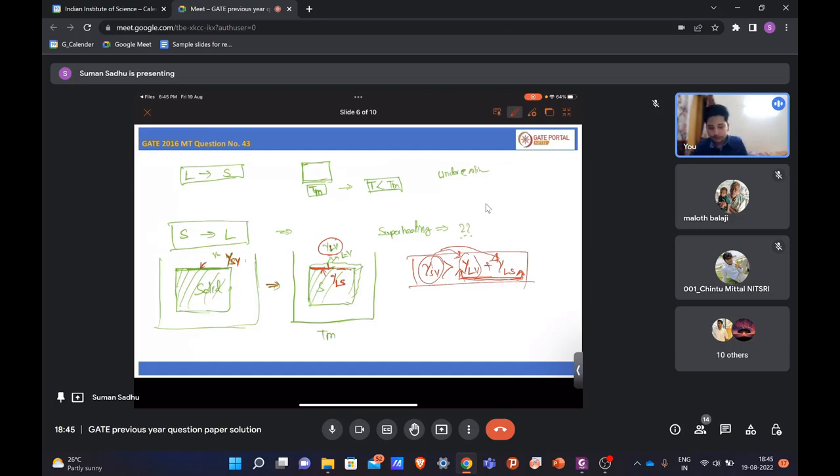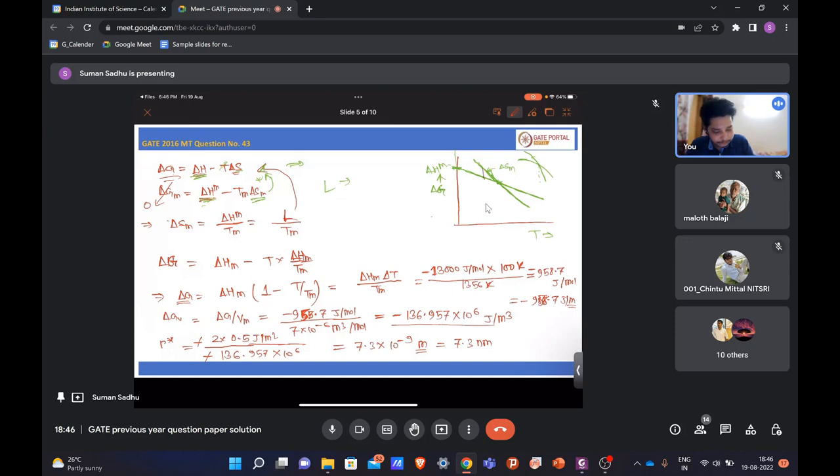But in the case of liquid to solid, the liquid-vapor interface is breaking, and you are forming solid-vapor plus liquid-solid. So in that case, what is happening? This energy is less. So when you go in this direction, you are going towards the higher energy things, meaning it will increase the energy of these interfaces. So that is not favorable. For this, you need to give a certain amount of driving force. That driving force is given by decreasing the temperature.